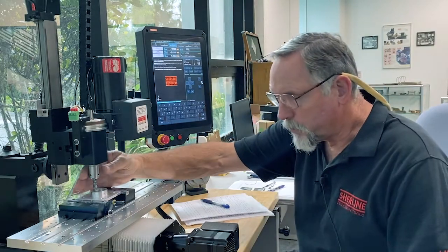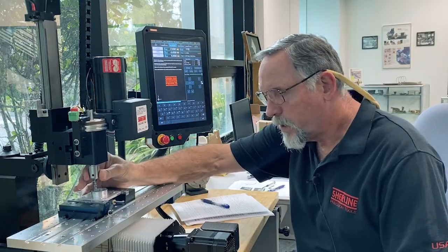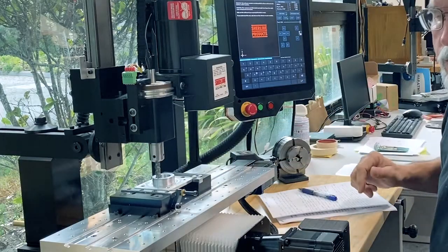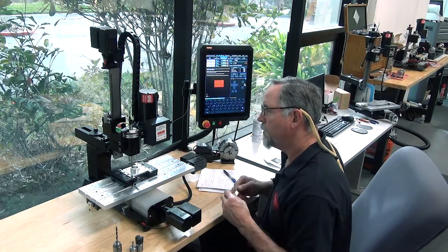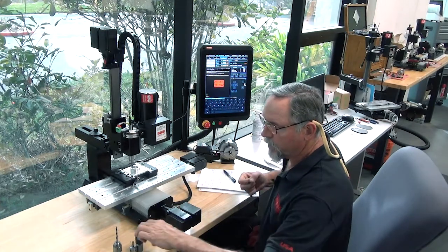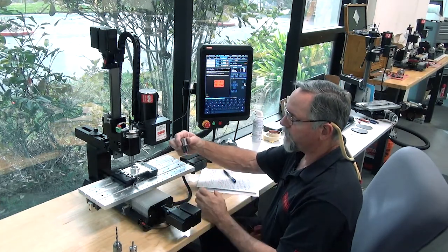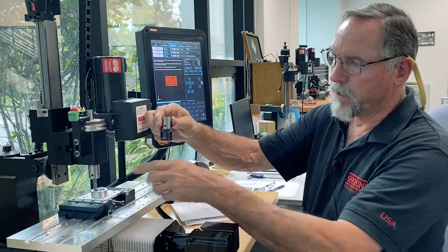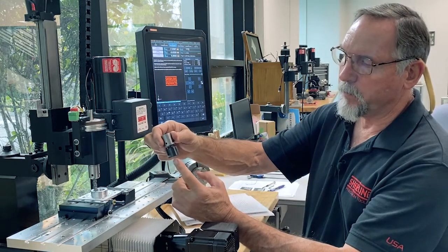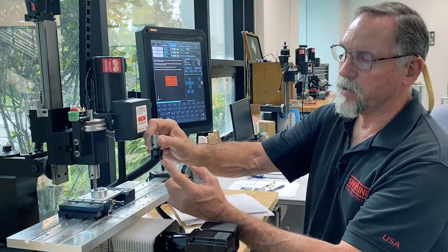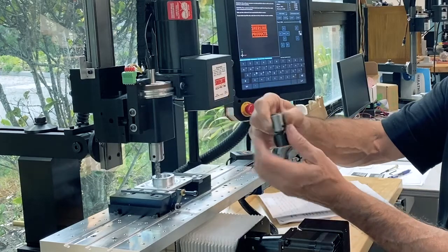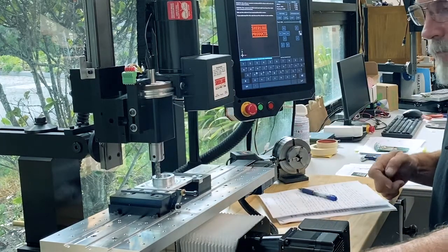On an end mill, you want to make sure that one of your flutes is actually over the surface of the part that you're going to touch on, because the end mill is relieved into the middle. The same would go if I was doing my face mill cutter. If I came down right now, it would be in the middle. You want to make sure that the actual cutting tip of the insert is over the top of the part when you're touching off.